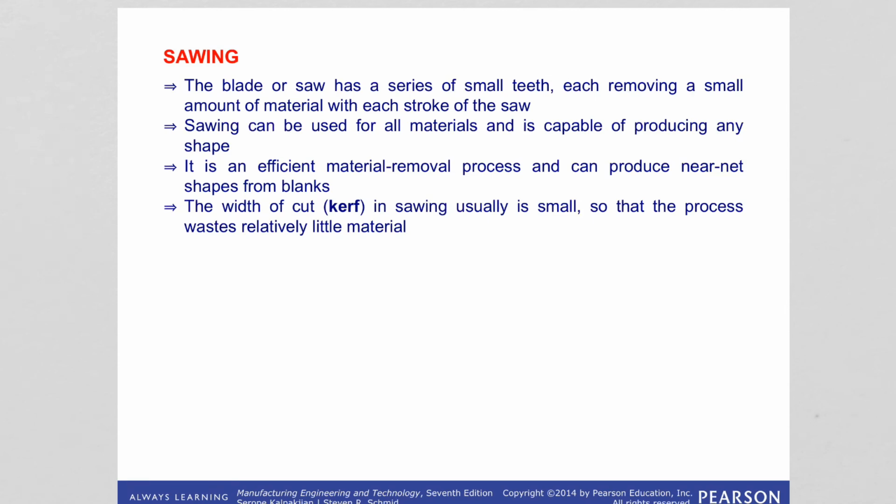It can be used for all materials and is capable of producing any shape. The width of cut, which we call kerf, is small, so the process therefore wastes only little material. Concerning this, we can say this process is economical compared to other machining processes because it wastes little material.